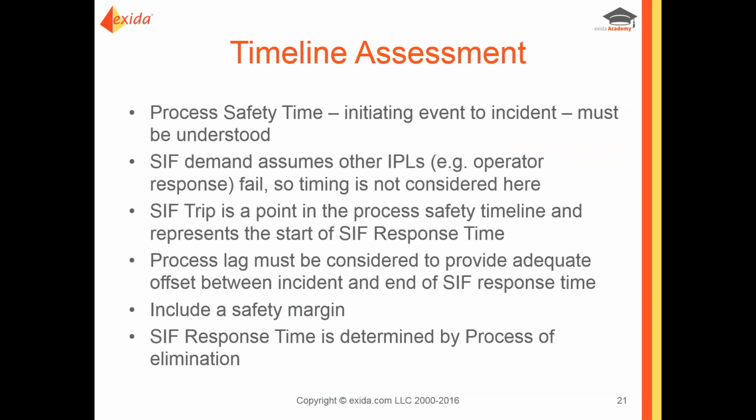So, looking at how we would break the different pieces of the overall timeline down, process safety time, from the initiating event to the incident, needs to be well understood and may need to be modeled. This may be a very difficult item to model because you require a firm understanding of the process and an understanding of the dynamics. There's engineering judgment involved to look at the rate at which steps may occur along the escalation of the scenario. So you definitely need to involve process engineers in this.